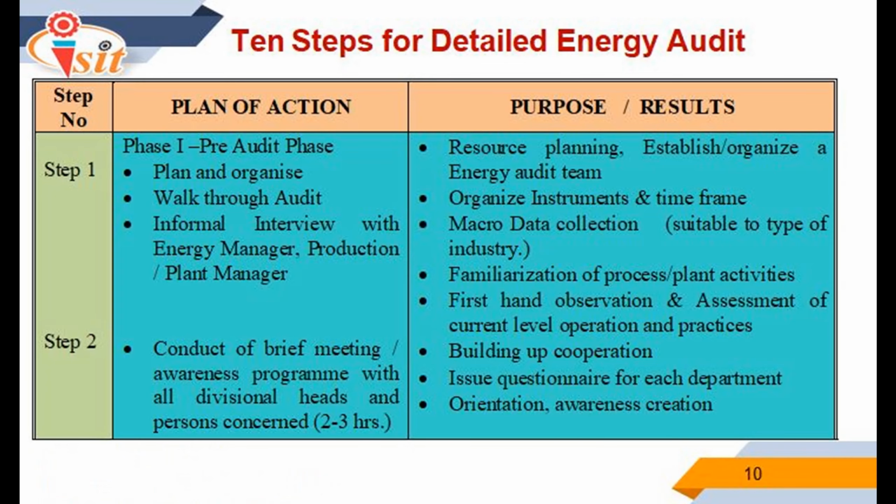The next important point is the 10-step methodology for detailed energy audit. It consists of three basic phases. Phase 1 is the pre-audit phase, covering step 1 and step 2. In step 1, the plan of action is to plan and organize, walkthrough audit, and informal interview with the energy manager and production in charge. The purpose of step 1 is resource planning and establishing the energy audit team.